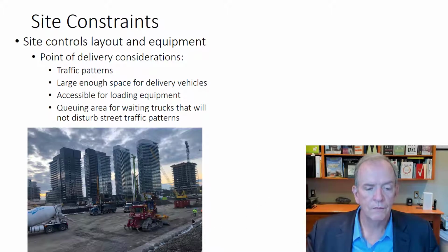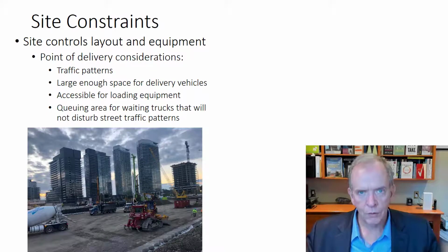It doesn't take very long for one of these to be filled, and so there's a continuous stream. Trick is not to have too many. You don't want to have too many lined up, because that's waiting and that's waste. So ideally, a perfect system would be, you have one truck waiting here, you've got one already backed into position, so that when this one pulls out, it just backs straight in. Not that it drives in, turns around, and backs up, and then that makes the excavator wait. So you're looking for this continuous flow of work as much as possible within reason.